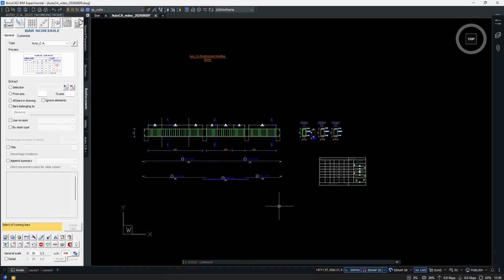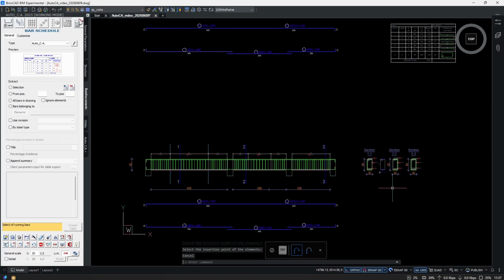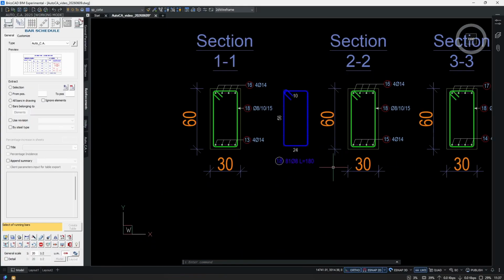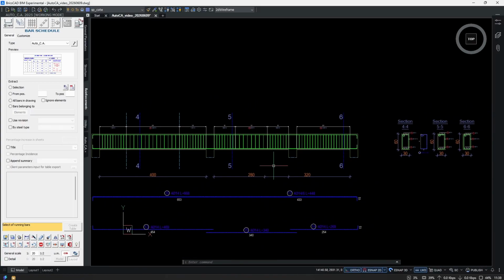But what if I want to copy it and change its dimensions? Well, as I said, these are macros which you can reuse and edit. So let's try this. I'm gonna copy everything that belongs to this one. Now we have another concrete beam with the same dimensions. I'm gonna rename these sections. So let's say that we want a 25 by 30 centimeter beam.